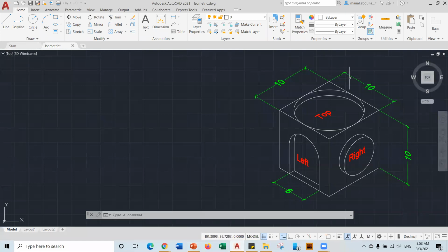In this exercise, we're gonna draw this cube. We're gonna create arc, as you see here. We're gonna create circles on the top, circles on the right. We're gonna give some depth here as we're gonna copy the circle just to make it visually going down. And we're gonna make it going to the right side to get some depth for the right isoplane.